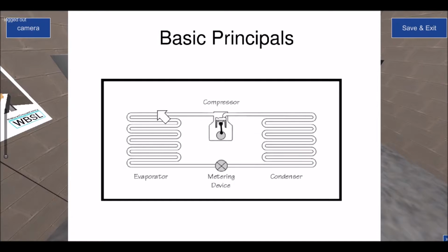So a vapor compression cycle is a sealed system. The refrigerant should never leave the system. There's no reason for the refrigerant ever to escape from the system other than if mankind makes a mistake. So in other words, human error is the only reason why refrigerant will leave the system, or maybe it's deliberate that humans will deliberately allow the refrigerant to escape. But it's a sealed system, and if you maintain it properly, there is no reason for refrigerant to escape other than wear and tear because of poor maintenance, or human error because they put a hole in it or stood on pipework or did whatever.